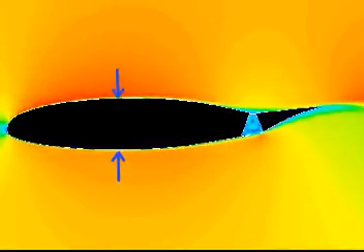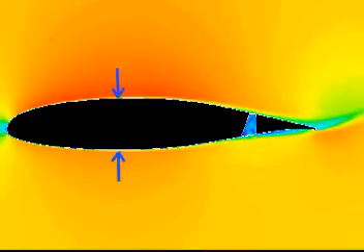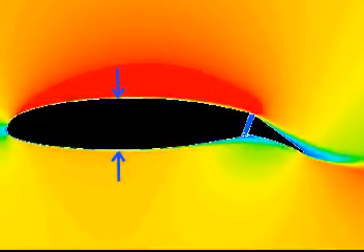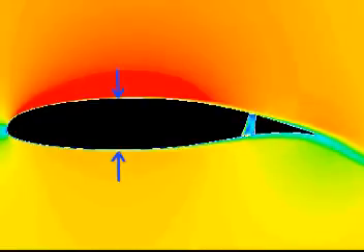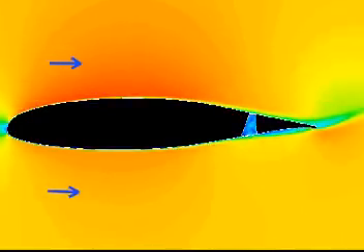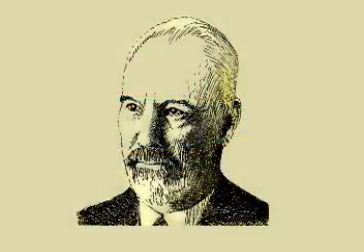This computational fluid dynamics, or CFD, animation shows colored contours of airspeed over a wing with an oscillating flap. Very close to the wing's surface is a thin layer known as the boundary layer. In it, viscous forces are important and cannot be ignored. However, outside the boundary layer, viscous forces are negligible compared to the inertia of the flow. We call this the outer, inviscid flow region. This distinction, due to Ludwig Prandtl, was one of the key developments in 20th century fluid mechanics.